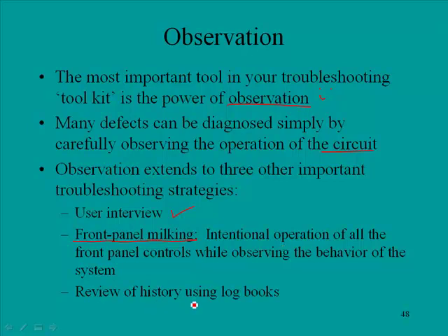Then review of history using logbooks. Logbooks can be of great value if they are maintained. Oftentimes, if a group of technicians maintains logs of the systems they're troubleshooting, they can diagnose weaknesses in the system. Then when a fault comes up, they can look in their logbooks and say, oh, that particular fault has been occurring frequently, and rather than do that, they can just go directly to the fault based on documentation.